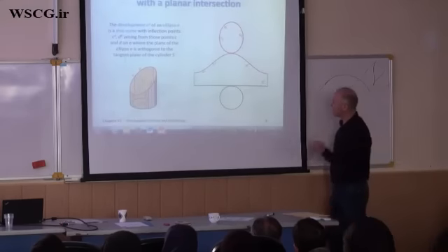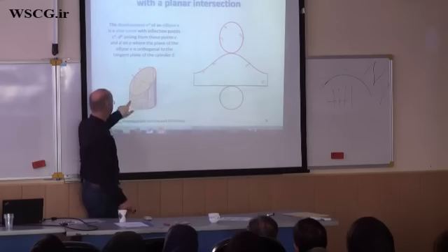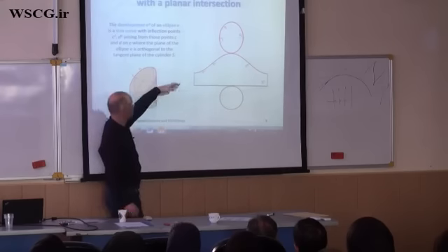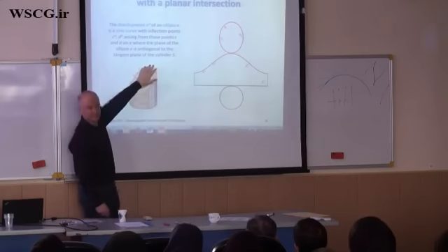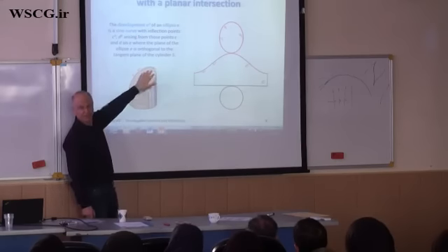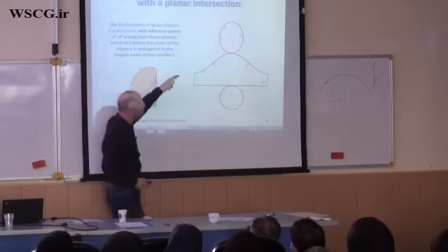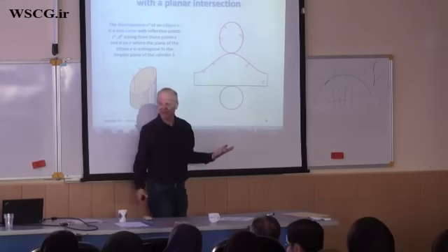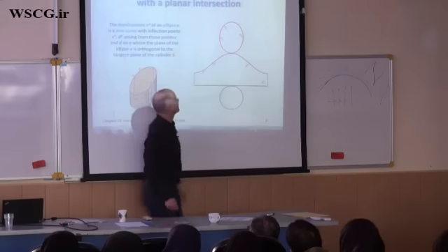Then, in a development, an orthogonal cross-section for this cylinder here, this base circle, maps to a straight line. If you take an oblique section of a right circular cylinder, you will get an ellipse, of course. And the ellipse, if you unroll it, is not a straight line anymore, right? Here you can prove it as a kind of sine curve.